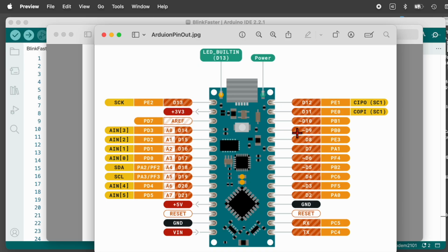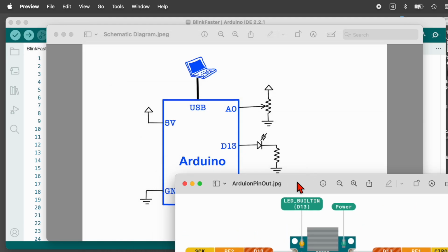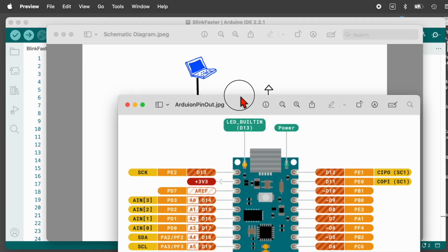These digital pins can be used either for input or output, but they're digital. They either transfer a 0 or a 1, with 0 being ground and 1 being 5 volts. There are also some additional pins over here, D14 through D21, which can also be used as analog input pins. When they're used as analog input, they're called A0 through A7. And the idea with the analog input is that the Arduino can read the voltage that's supplied to that pin and measure it. And so we'll be using A0 as our input to be measured in this little demo project.